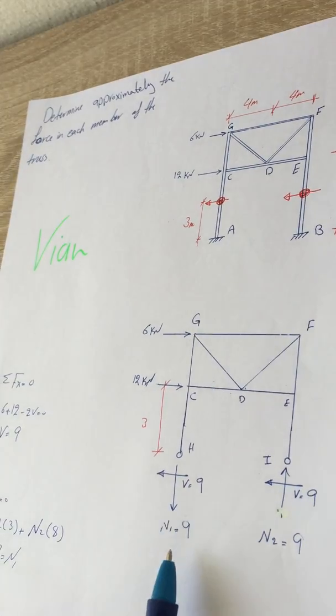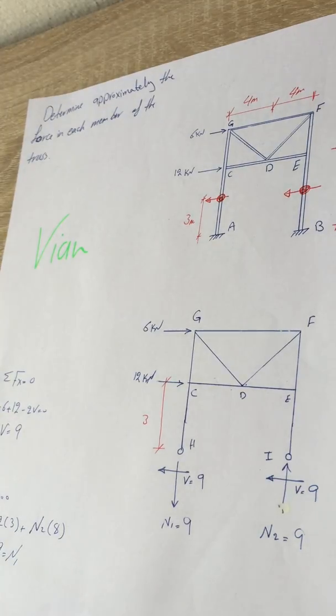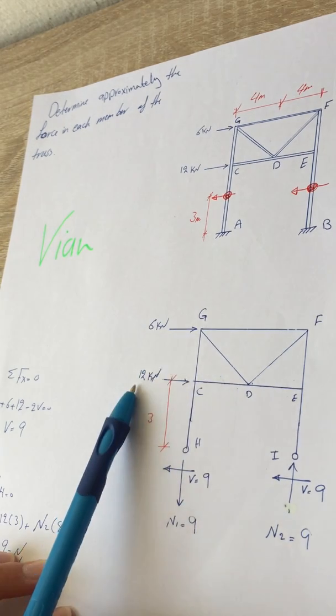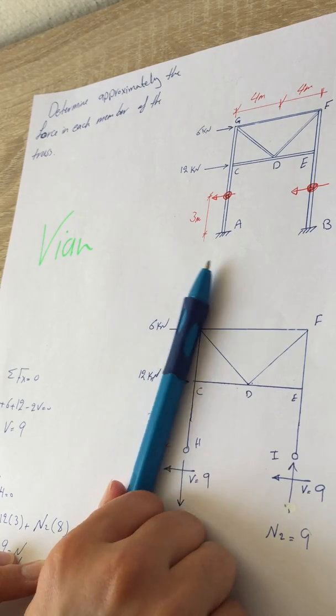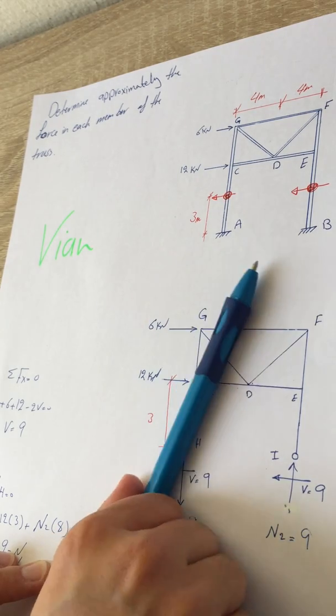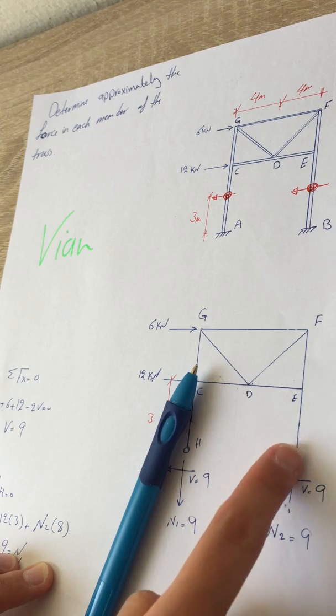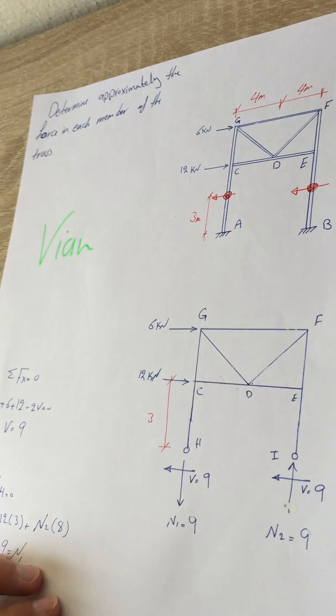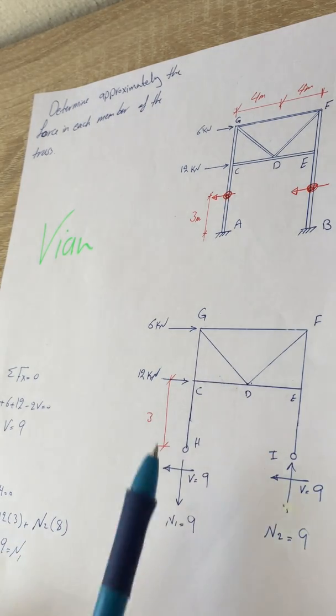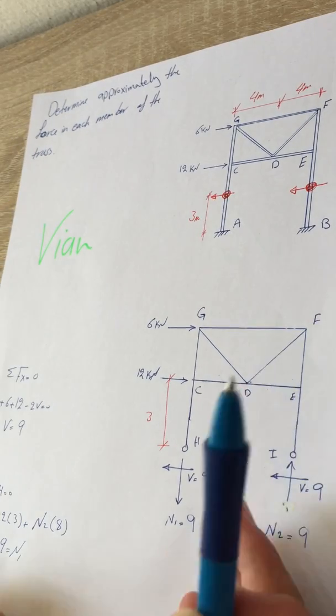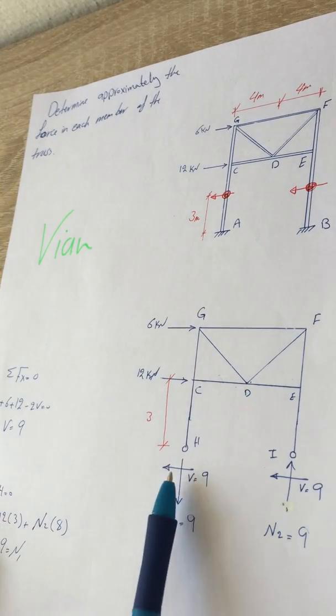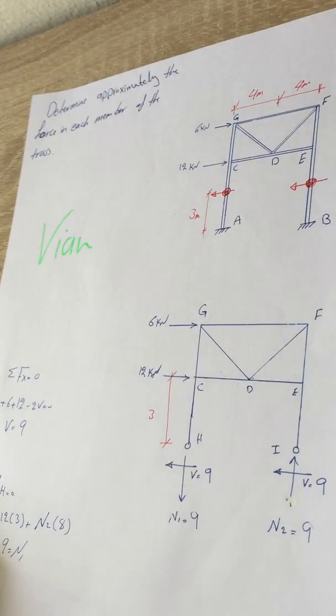And then for the normal, you have to pay attention to this. Just as we did in the cantilever method, we knew that one side is tension and the other side is compression. You see these two lateral loads, they're going to push the whole structure to that side. So this is going to be compression as the nature of the structure to prevent it from movement. It's going to be compression to push it so it wouldn't move, and this one is going to be in tension.